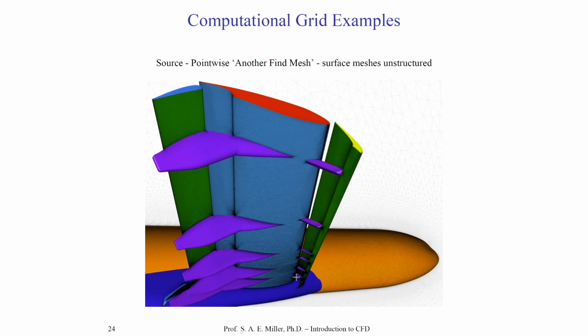When creating a mesh, you would initially define the surfaces and make them watertight. You make a watertight, without holes that is, domain of the fluid. On all the surfaces of that domain, you create surface meshes. From the surface meshes, you create an interior volume mesh. We'll be trying out this process multiple times in this class, but you can see, if you're able to see this on the compressed version of the video, there's also these grid points out here in the white area.